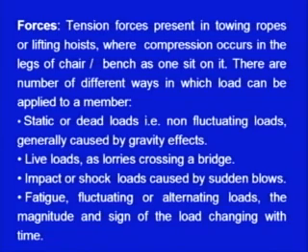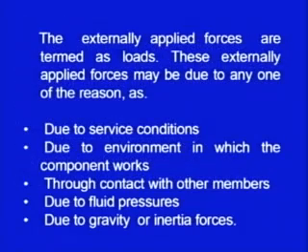As we discussed, the first one was the static and dead loads. That means the magnitude of the load is not changing with time. While the fatigue or fluctuating load is always changing. The magnitude is changing, or the way of application of the load is always changing with time. So fatigue, or you can say fluctuating or alternate loads, where the magnitude and the sign of the load change with time. This is the main load through which the failure of a machine always occurs.